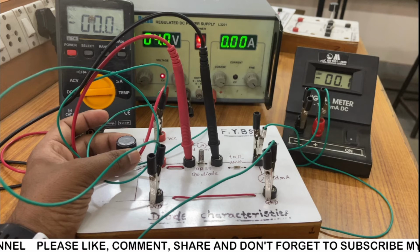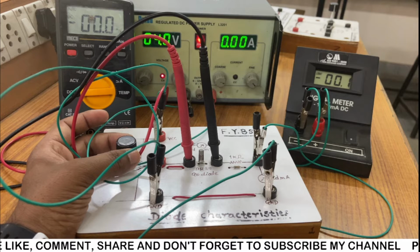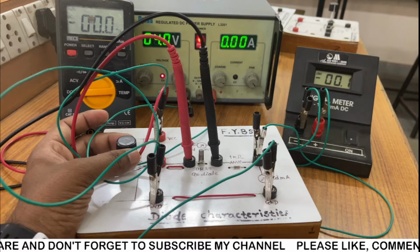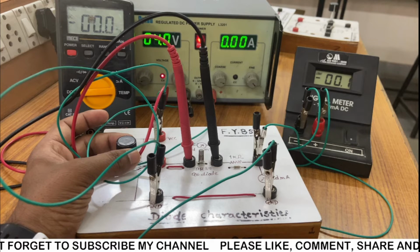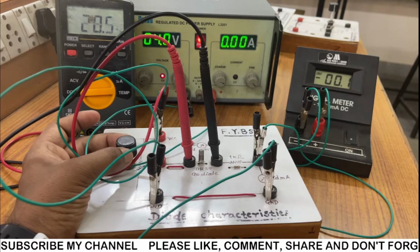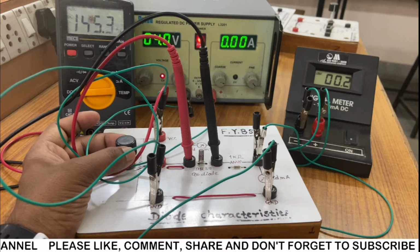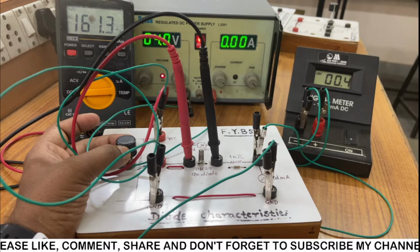Let's look at the circuit, where the potentiometer is used to vary the voltage across the diode. We are using a germanium diode DR25, so that it will give us a reading in milliamperes, which is the current. We vary the voltage from 50 millivolts onwards. You can pause the video and take the readings according to your observation table.